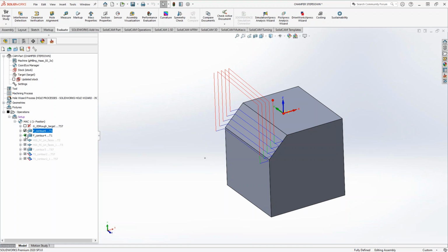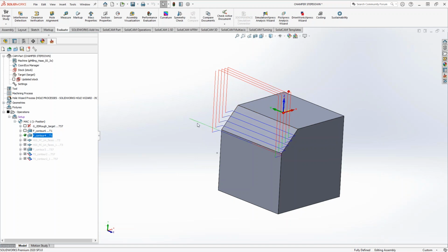And you can see there's a little bit of a different icon here between the two. These are actually the same toolpath, except this one has been edited slightly to have this movement right here. Now that movement is kind of not practical, but it's there just to show that I made an edit to that toolpath using the toolpath manager. So that icon just highlights the fact that that thing has been edited using the toolpath manager.